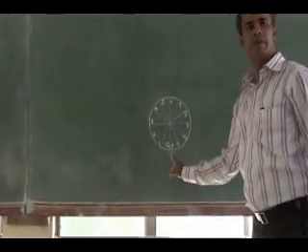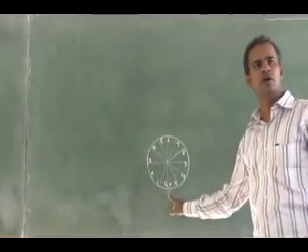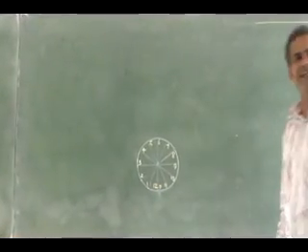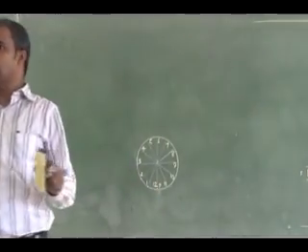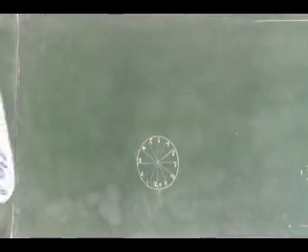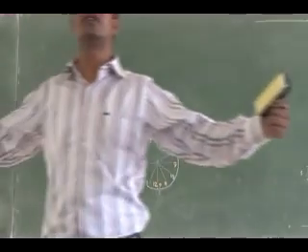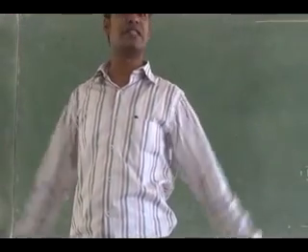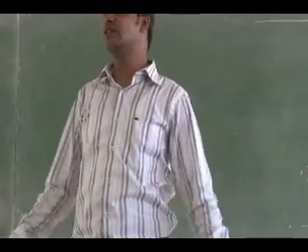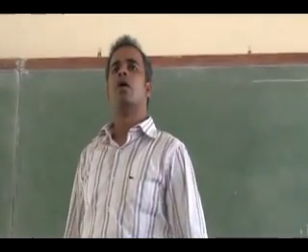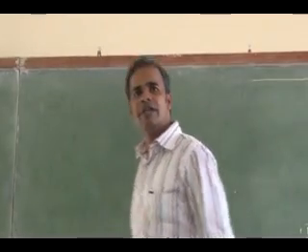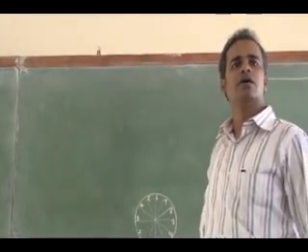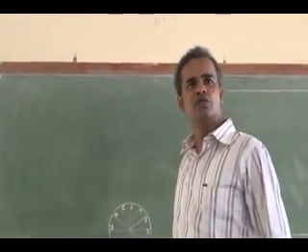Draw a horizontal line from point P, that is the 12th point. That is nothing but a tangent line. That is going to be the overall final length of the thread around the circle. What is the length of the thread around the circle? The circumference of the circle. What is the circumference of the circle here? 125.7, that is pi into d. Diameter is 40 mm here. 3.14 into 40 is 125.7.